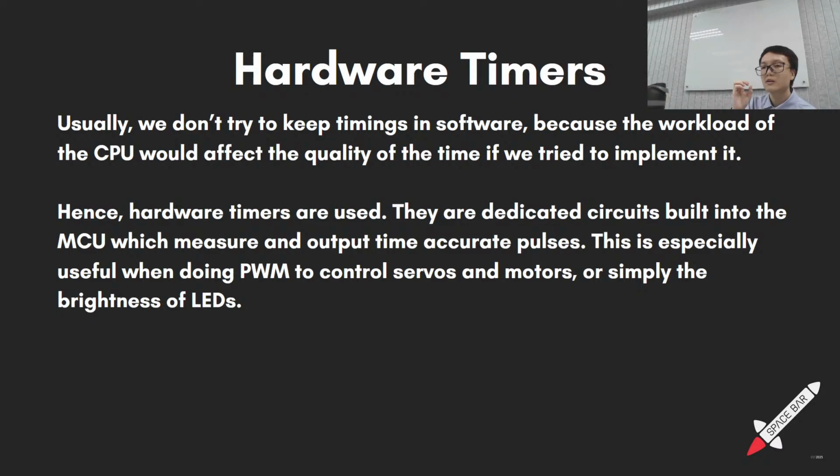With PWM, what really matters is the duty cycle, which is the time on over the total time multiplied by 100%. This determines how bright the LED is.